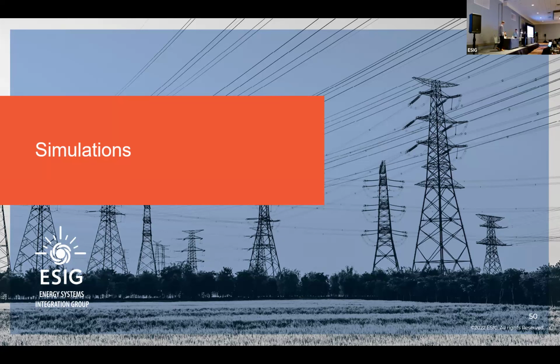So it is a change in the plant that may potentially affect the model, but is it practical to update the model every time they swap one inverter or add one inverter? That's probably not. So we're trying to figure out what frequency makes sense. I think also the MOD-026 NERC standard will probably have some frequency timeline there, but we are still figuring it out.